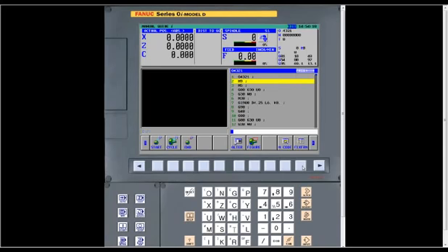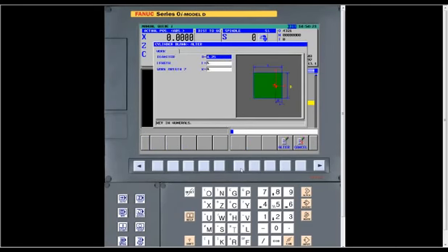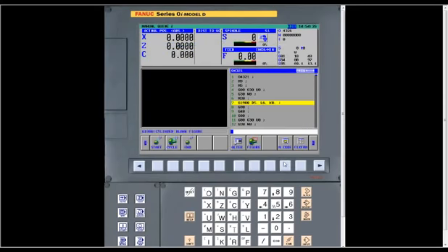Like the program I have called up here, if you arrow down to where it says cylinder blank figure, or whatever figure you have, you press the Alter soft key. See, it takes it back to within that cycle. Then, like, I have 4 1/4 for the diameter. If I put 5.0, input that, and say Alter, you see it change it in the program.